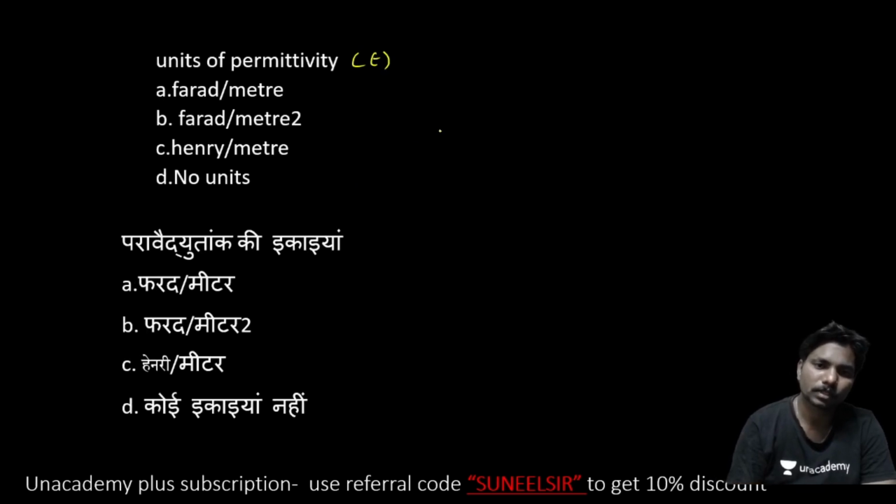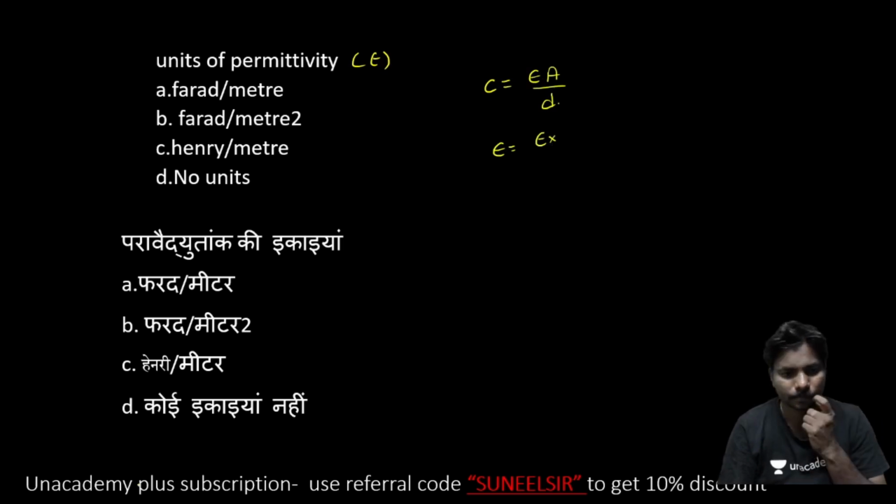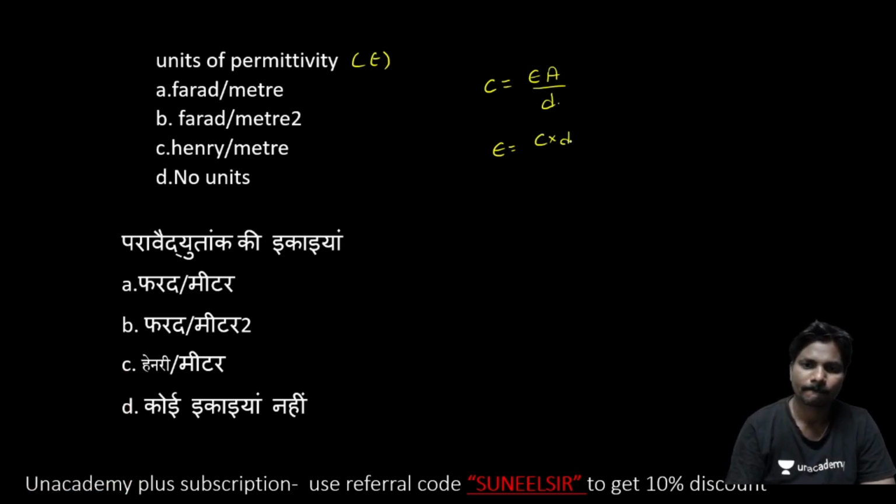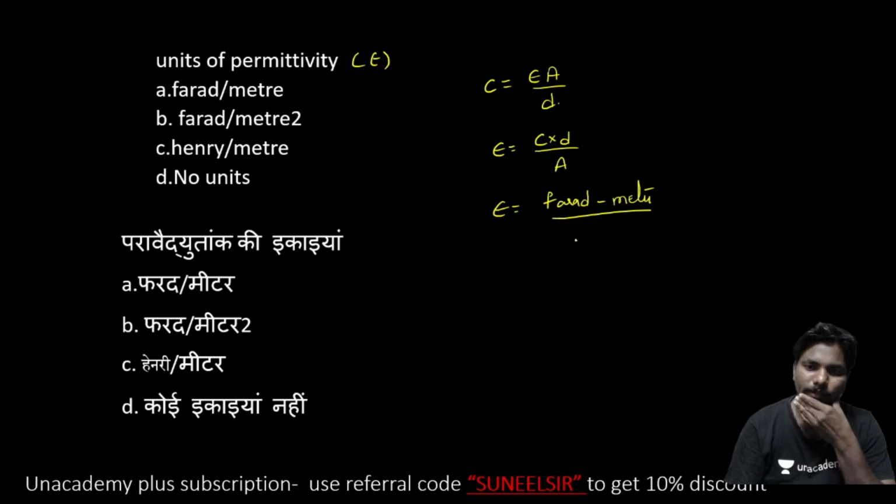Units of permittivity, epsilon. We have epsilon in the capacitance, C is equal to epsilon A by D. So epsilon is equal to C into D by A. C is capacitance in farad, D is distance in meter, A is area in meter squared. One meter gets cancelled out.